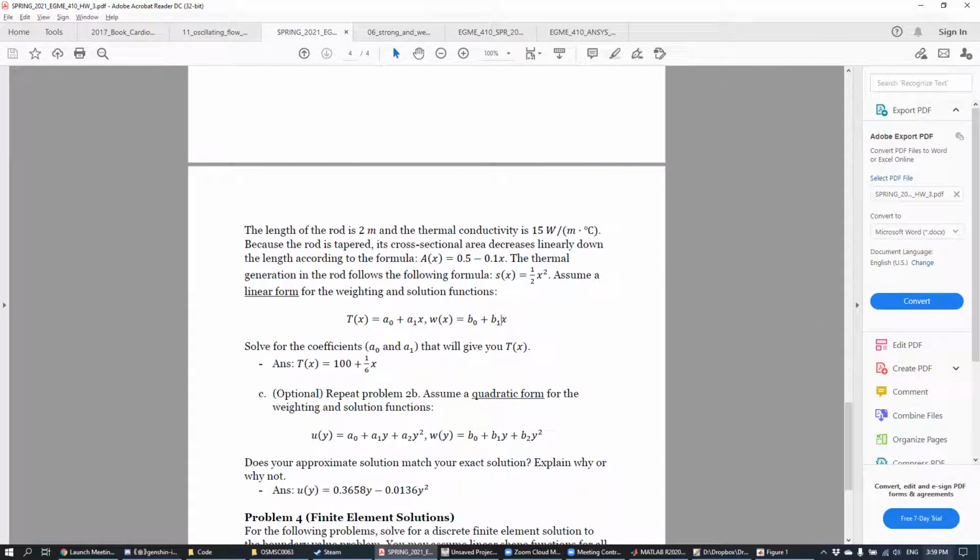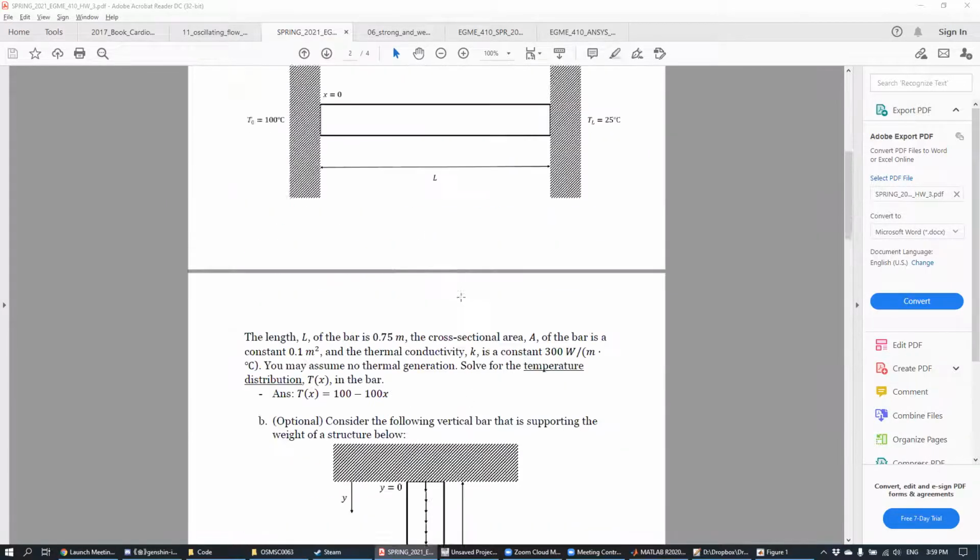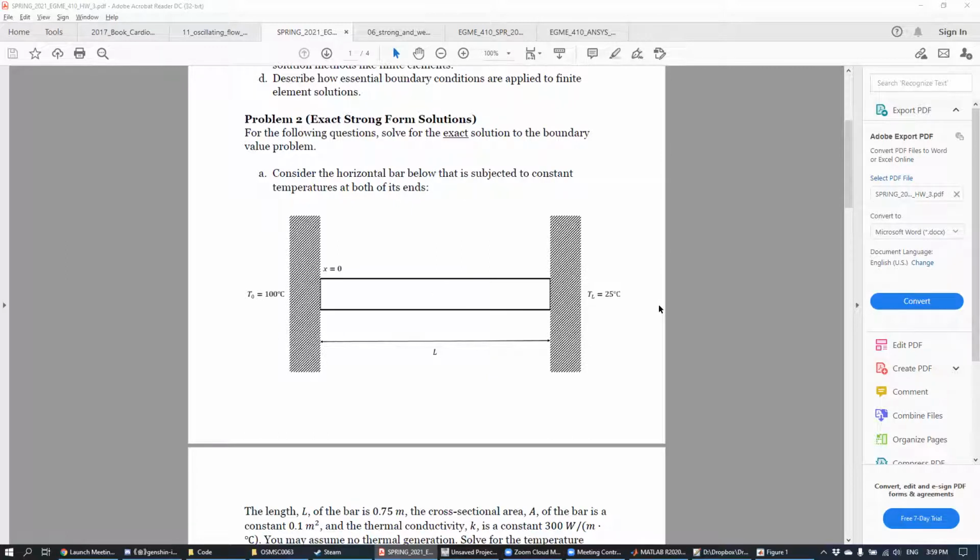So I know that the condition for the weighting function I saw in the notes was that it's zero at the... I forgot the name of the boundary condition. The Dirichlet boundary. Yeah. So it's zero there. So then for our problem, I think it was problem 3 where both sides had the temperature displayed. That was our boundary condition. Would then the weighting function be zero at both sides? Yes. So you would apply it twice, and so you'd have it be zero here, and you would have it be zero here as well.